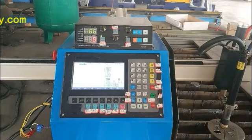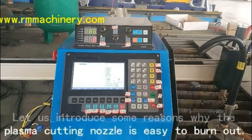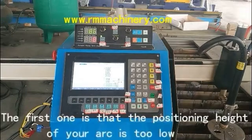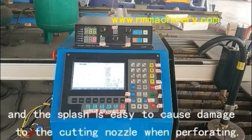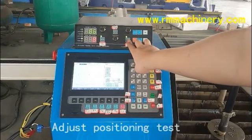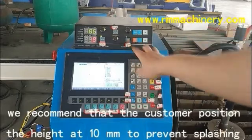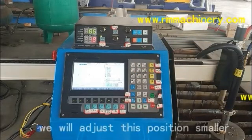Let us introduce some reasons why the plasma cutting nozzle is easy to burn out. The first one is that the positioning height of your arc is too low, and the splash is easy to cause damage to the cutting nozzle when perforating. Let's try this height. Adjust positioning test. Under normal circumstances, we recommend that the customer set the positioning height at 10 mm to prevent splashing.